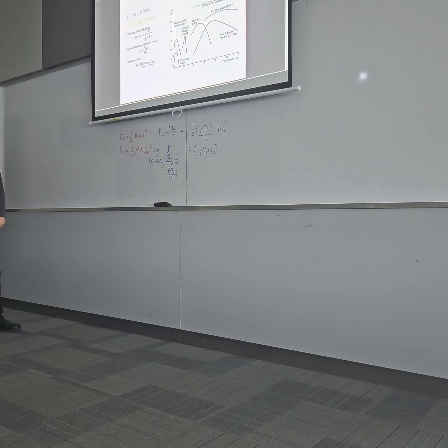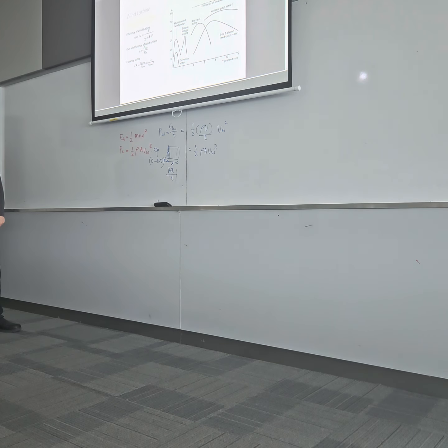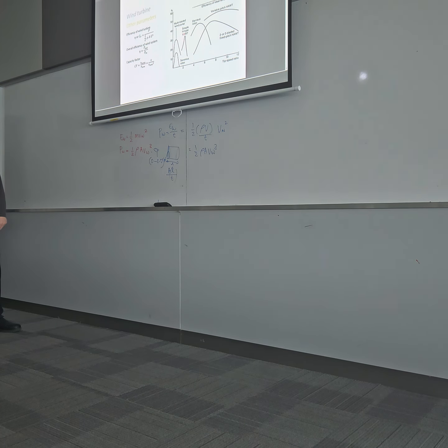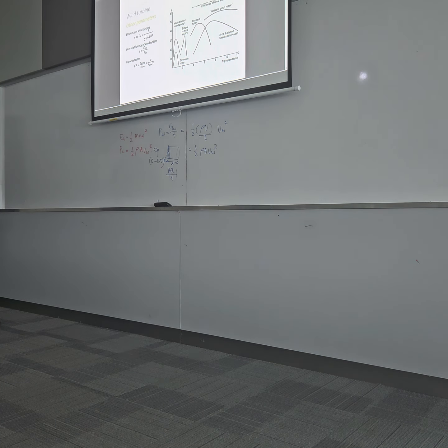So a fixed pitch horizontal axis wind turbine could be operating somewhere around here. Okay, whereas a simple H-type vertical axis wind turbine is all in the lower range. Okay, so this is only within the 13%, as we saw here. We only reach a certain portion of it. Okay, so these are the overall efficiencies. We can see the horizontal axis are more or less in the higher range of the efficiency side.